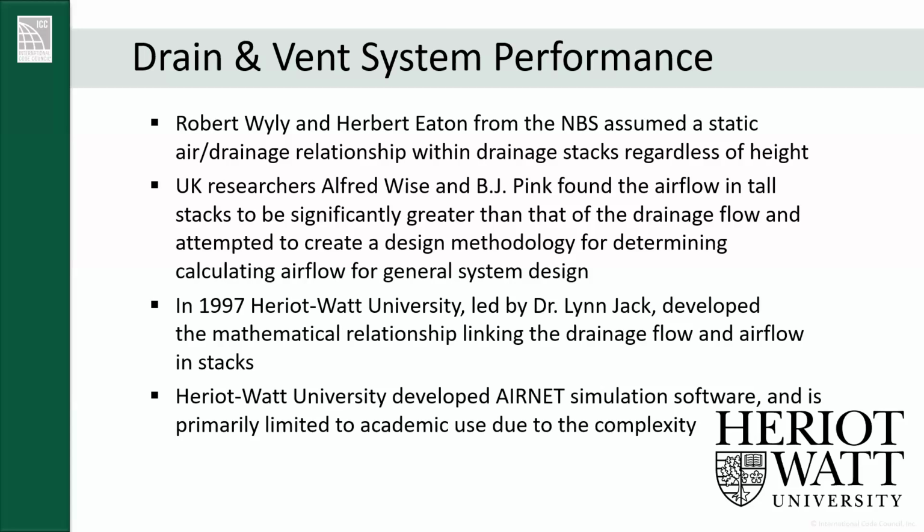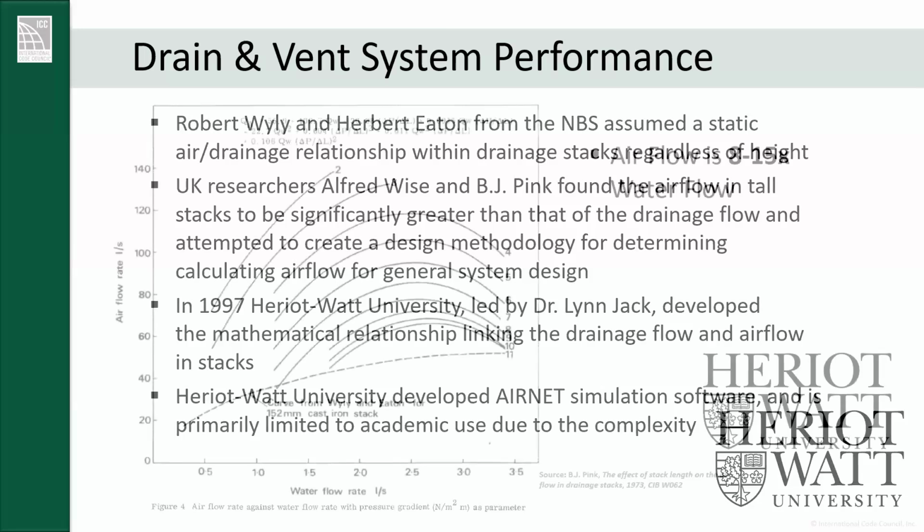Dubai, where the Burj Khalifa building is, which I think is one of the tallest buildings out there. They have issues with traps being blown out of toilets, or traps having negative pressure, because the water in the drain actually approaches terminal velocity, a couple hundred miles an hour going down, because it's going down so far. Yeah. So we're going to be working with them on that.